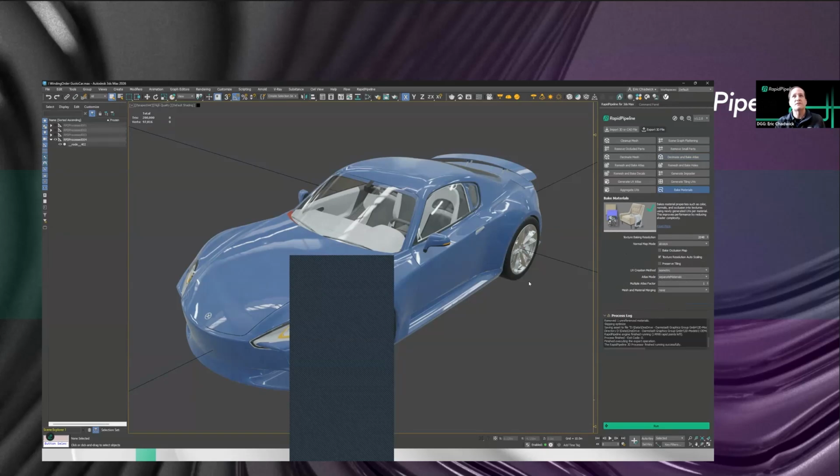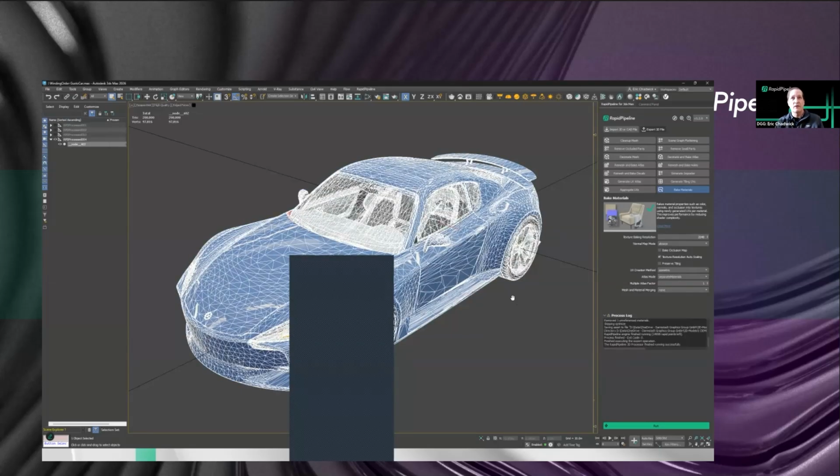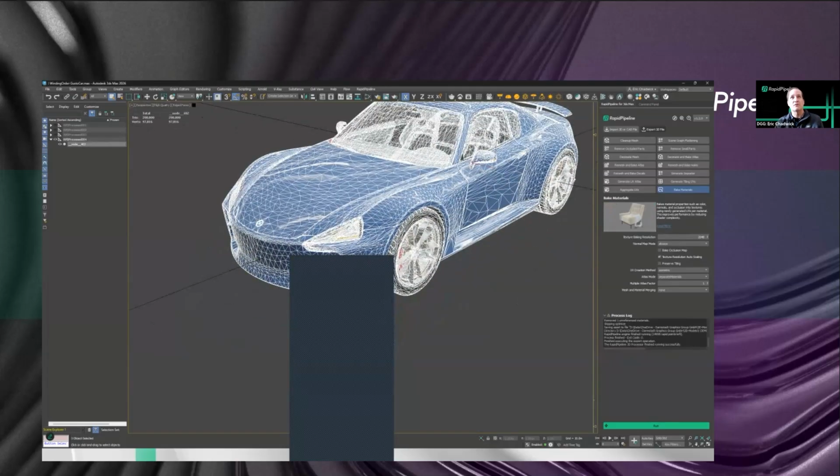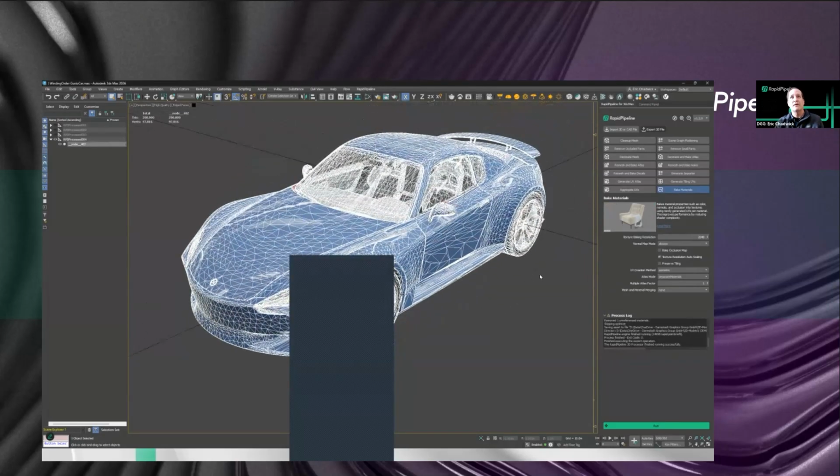In that case, it's only looking at all the surfaces that comprise that material and baking that as one whole. For example, the tires would render as one material, all those tires would be one, and the paint would be a separate material and bake on its own. That's a way to avoid ray misses or things interpenetrating each other in the bakes.